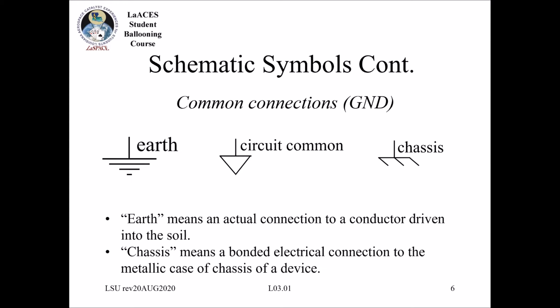In general, if I'm using a digital circuit, I like to not be connected to earth ground. Ideally, the ground that I'm using is isolated from earth ground, because you can get those power spikes. It's not the cleanest signal. That may be something you can check on your power supply with your multimeter, to see if the earth ground and your common ground are isolated. You can check the resistance between the two of them. And if there's no resistance reading, or it's a really high value, that means they're isolated.